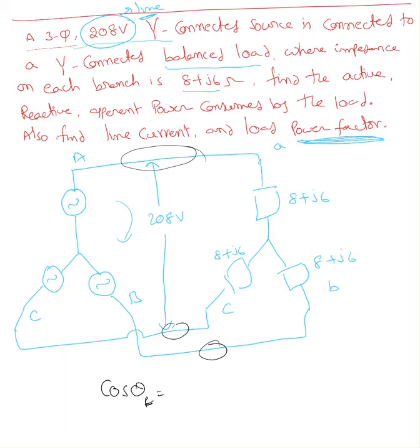Most of it comes from nearby, though not necessarily 100%. But assume that it is coming from a nearby power plant, which is 15 to 20 miles away from our university. Over those 15 miles we're running a wire. That wire is going to have some resistance as well as reactance. So that's what we represent here as a line impedance.